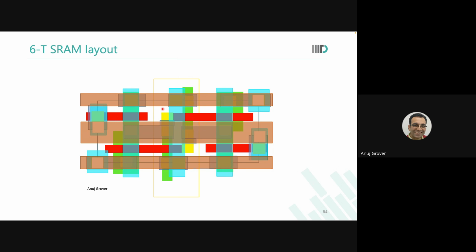Okay, so this question is more about sizing, that part of it. His question is that in the lectures, there was a reference that in 65 nanometer technology, the gate length that you should keep is 80 to 90. Why do you think we need to do that? This question is for 65 nanometer. So in any technology, in 65 you will keep it 80 or 90, in 45 you will keep it 55 or 60, in 32 you will keep it around 40. Why do you do that?